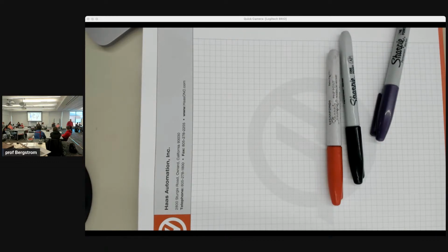Press cycle start, let it happen. If it says negative 0.6215, and it looks like it's an inch away from the part, and it's still doing rapid Z down, yeah, it's probably going to crash, right? So at this moment, feed hold and reset is enough, but because of the frustration of that moment of realizing I screwed up the offsets, I usually hit the E-stop just out of frustration. But it doesn't have to be in earnest.